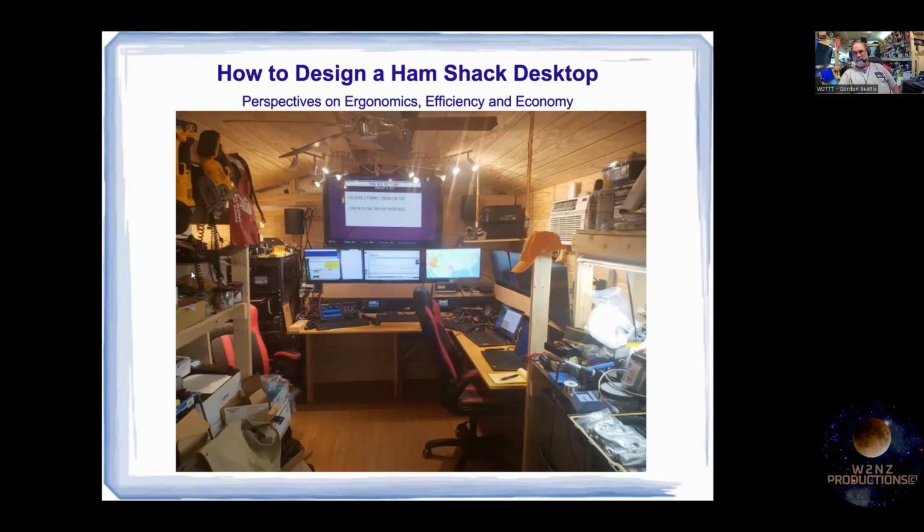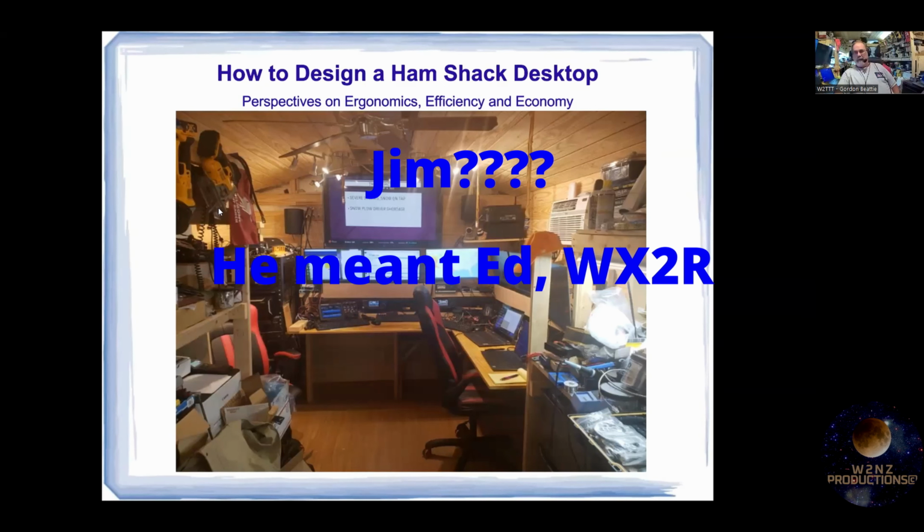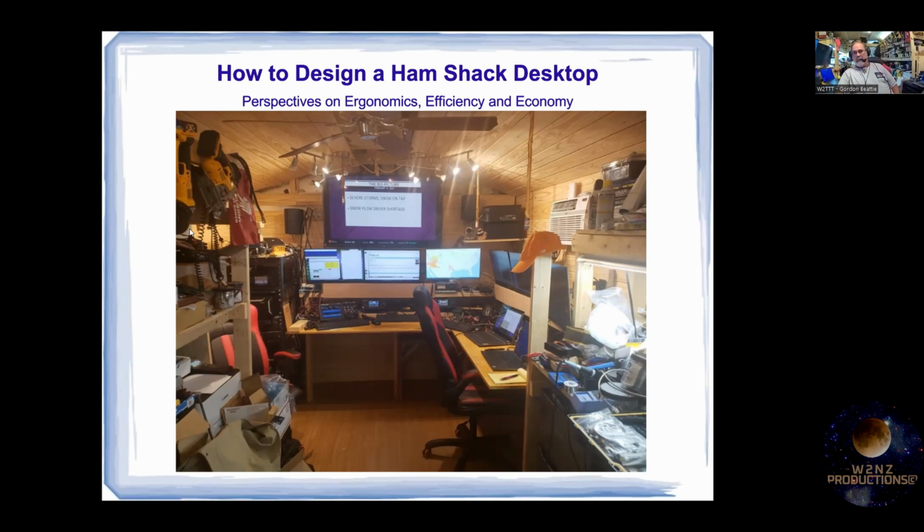And the other thing is, and you can't see it, but you see this piece of aluminum that's here, Jim? It's aluminum angle. It goes across the top of the, actually you can see the gray box, the power box. It goes to the corner. I cut it and bent it. It ultimately is now bonded to these antenna entry points, but the antenna entry points are also grounded outside where the lightning arresters are. Lightning arresters are actually about 6 feet down and behind this entry panel here. So there's no lightning arresters here. They're on the ring ground about 8 inches off the ground in a separate box outside. I could do a whole talk on the outside just by itself another day, but that's a good question.